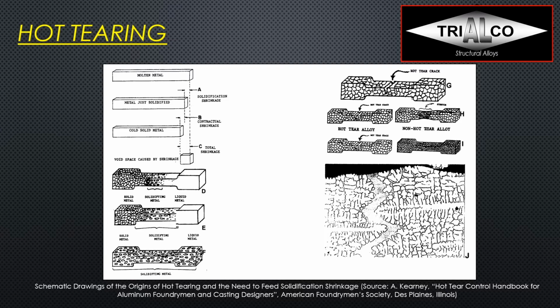Now, hot tearing, and that's a tricky thing. So everybody knows that when something is hot, it's bigger than when it's cold. And when metals solidify, it actually shrinks. And most aluminum foundry alloys shrink by 6, 7, 8% easily. So we would have to basically design a part that it can easily shrink by that amount, well, without being obstructed and causing it to crack.